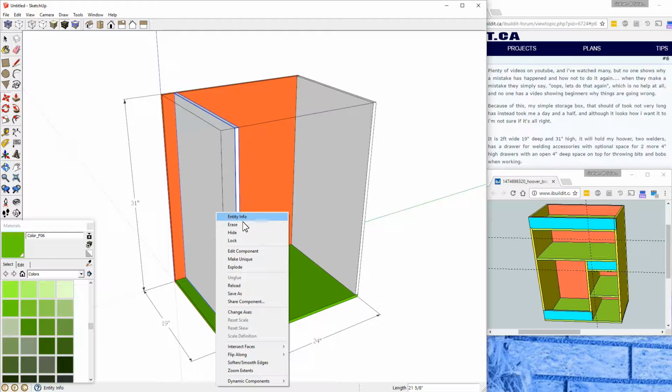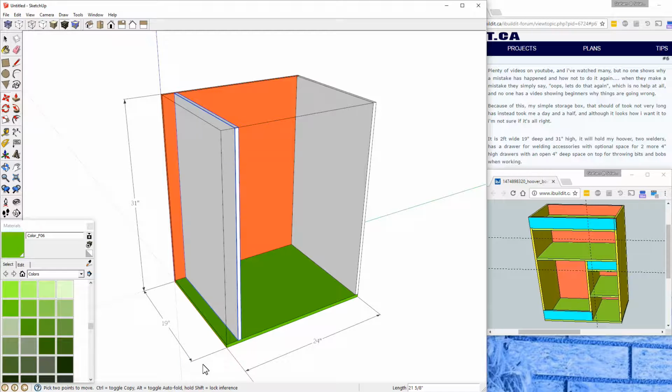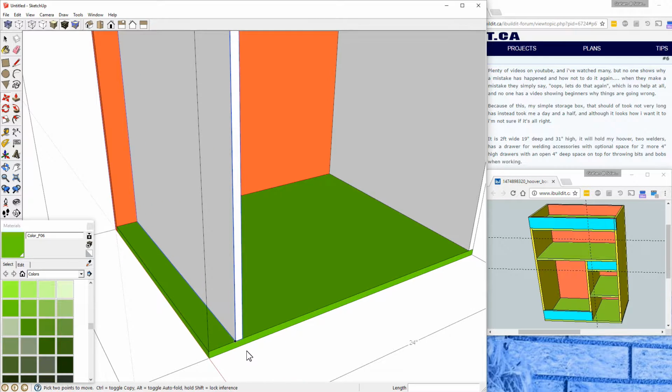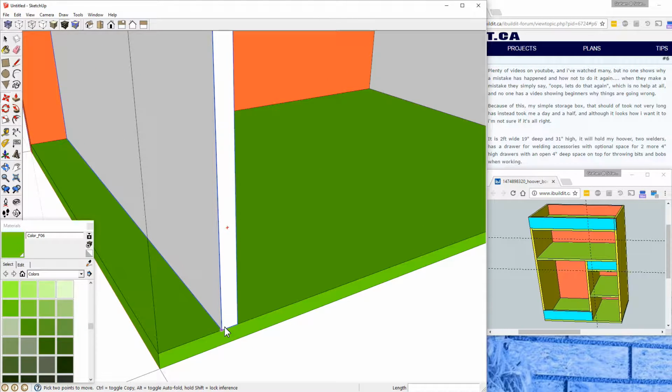And I'm also going to flip along the direction that I've moved. That's useful. We won't see it in this project, but if you're using things like dados and so on, by flipping, essentially creating a mirror image, it means that later on when you start cutting the grooves, they're cut on the inside face of both pieces.